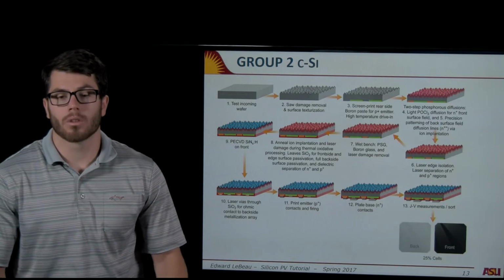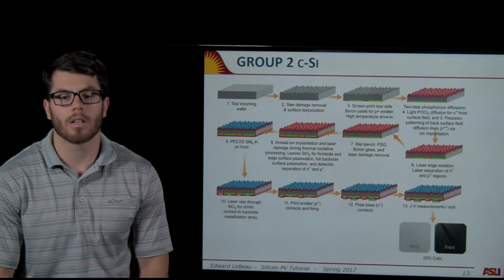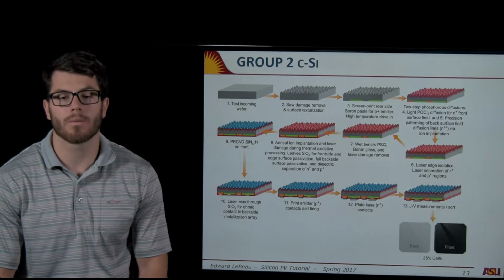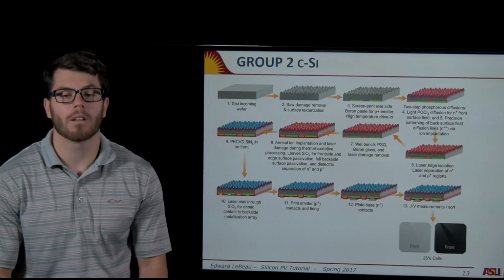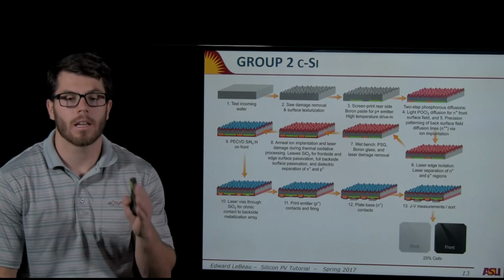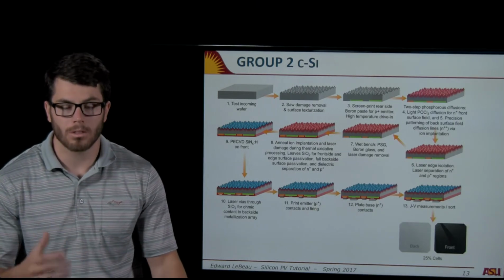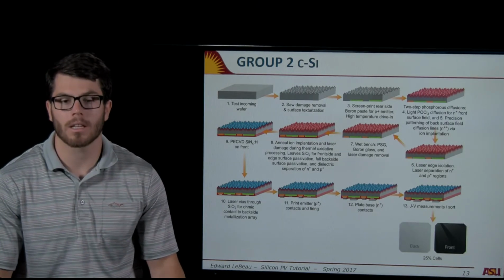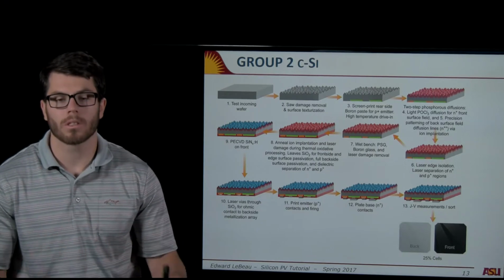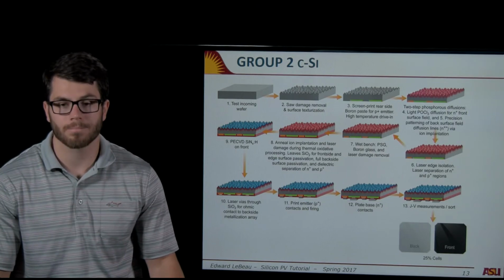So now let's look at this. This is a Group 2 silicon solar cell. This is actually called an IBC, which is an interdigitated back contact solar cell. So there's no front contacts, which increases the efficiency, but adds some complications to your processing. So the back side has these N and P wells going on, which means you need a more sophisticated diffusion process and things like that. So we've increased the complication of building yet again, but we've increased our efficiency to 25%.